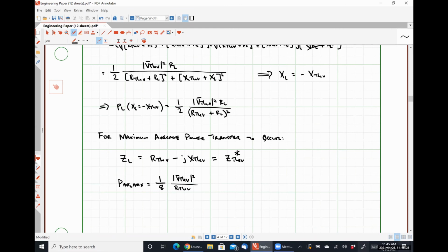Okay. So I would suggest putting on there, as a reference, how to do voltage division, how to do current division, how to do source transformations and things like that. Maybe an example of using superposition as well, if it's something that you're not super familiar with. So that would be one side, just the basics of how to do steady state sinusoidal circuit analysis. Also obviously put on there how to convert from the time domain to the frequency domain and vice versa.